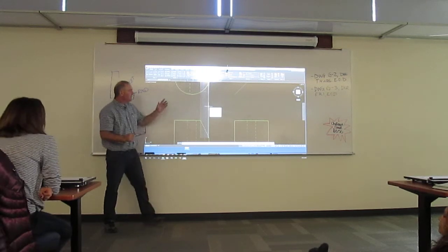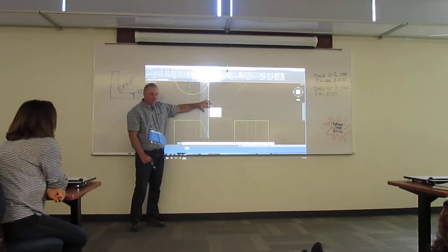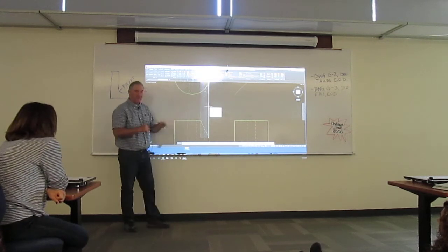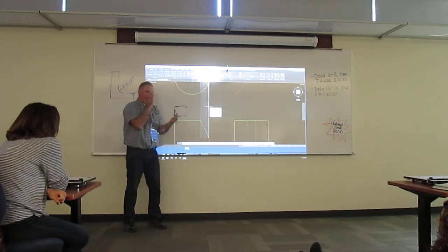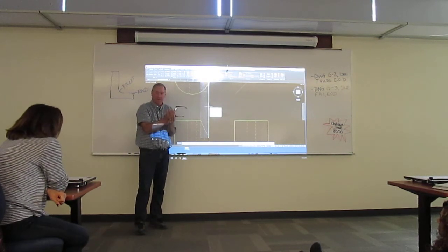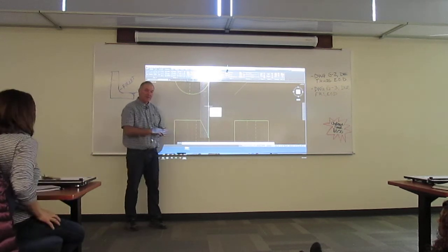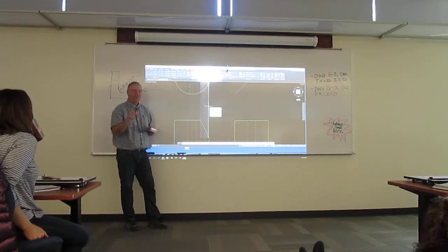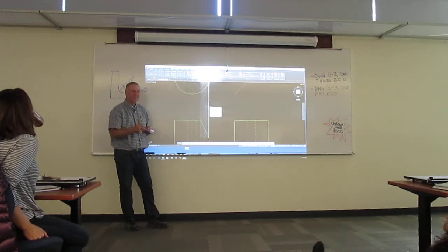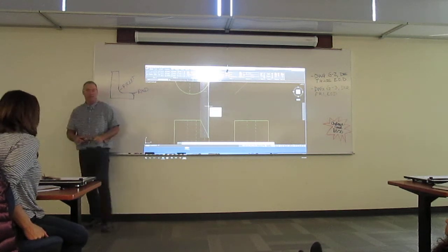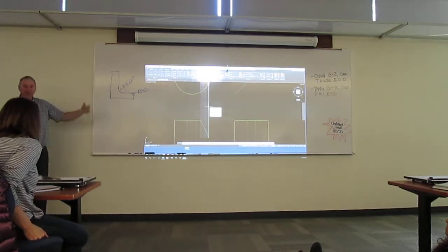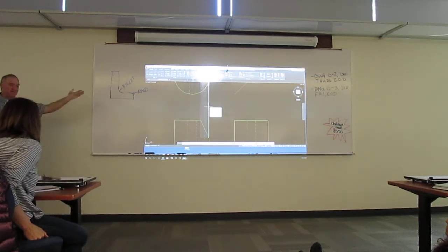Keep in mind, when you do this method and you approximate a shape, when we get to the dimensioning portion, I'll make a big point of this. You're going to dimension where these points are if you want it built like this, because the person that's constructing this thing is only going to be as accurate as how many data points you give them to build the curve. And they'll do it just like we do here. Sheet metal workers for heating and air companies do this stuff every day. And they're used to this, so they'll see it and be able to replicate these.